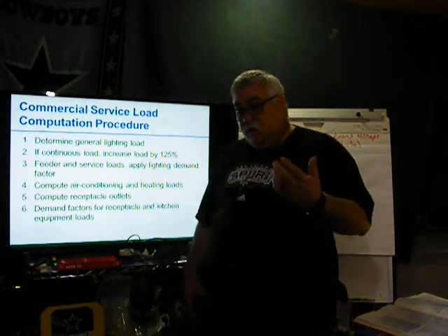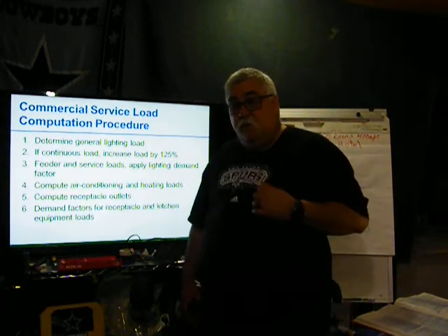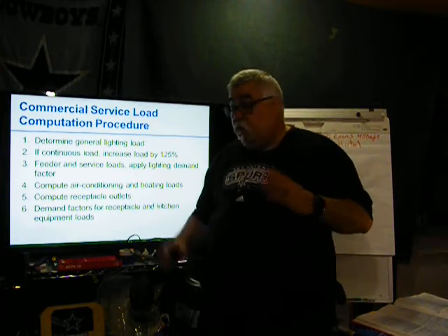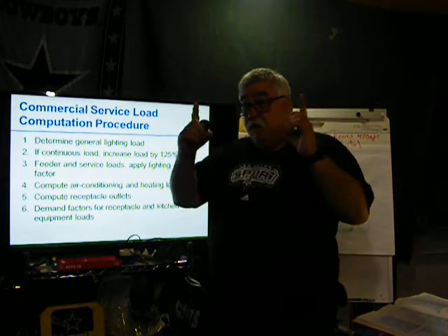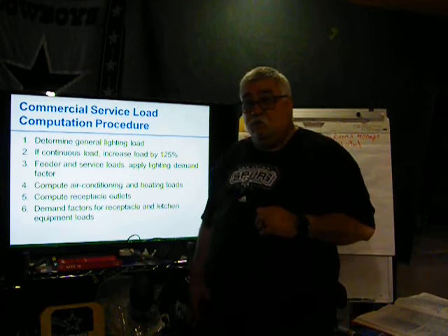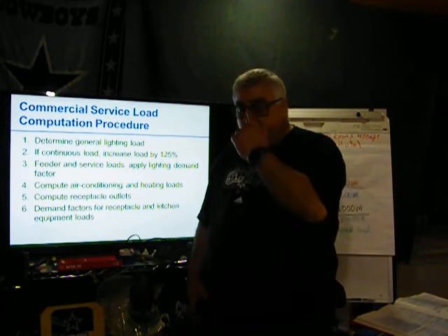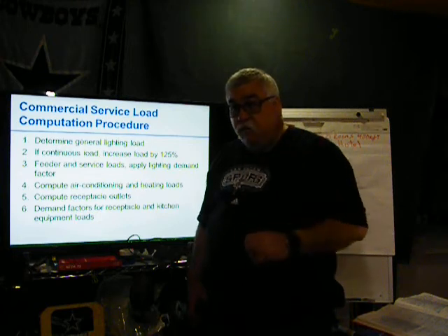If the wire size is a pretty large number, you maybe want to do it in parallel. You can. Remember, when it's in parallel, it has to be size 1/0 or larger, and they all have to be the same length. So always remember that. So in parallel, it has to be 1/0 or larger.